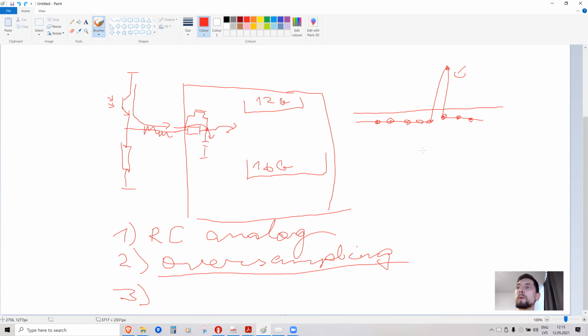So it is a common practice that some people, when they make a digital filter, they just remove outliers. So if the average is this, and there's a point that is very high or very low, then it just gets discarded and the average is calculated from the rest of the points. So let's make such a filter.